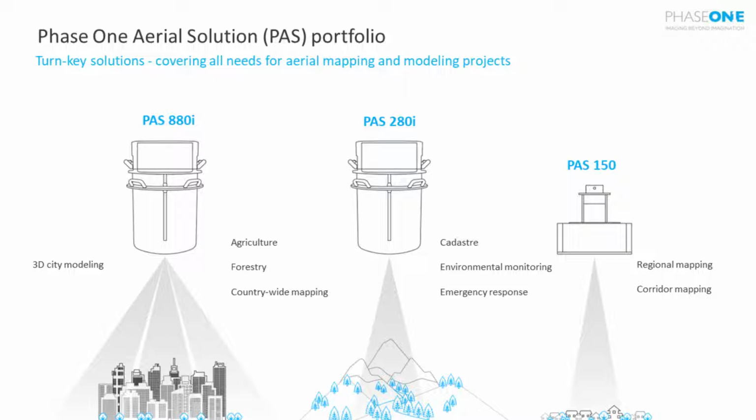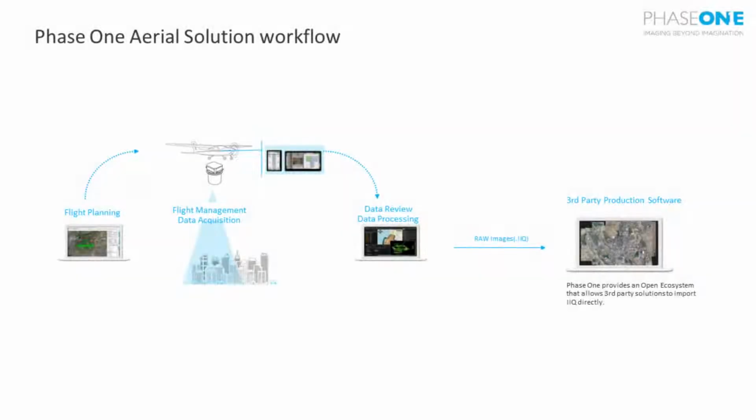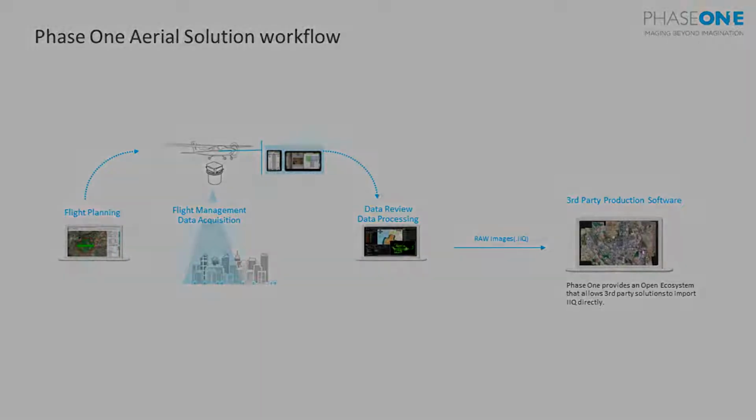A component of that is the camera, which has got to be a calibrated camera. You also need a quality GPS antenna and an airborne GPS solution, whether it's PPK or RTK. With that, you have to have a very, very good IMU. All three of those things, as part of that system integration, give you what we see in a past system, along with the software that Will is talking about. With all that, you can get some absolutely fine data.